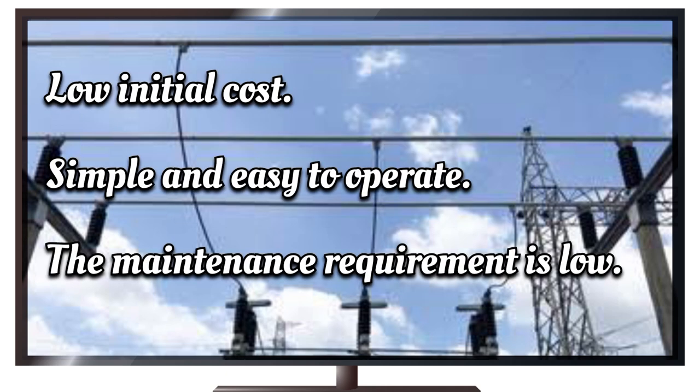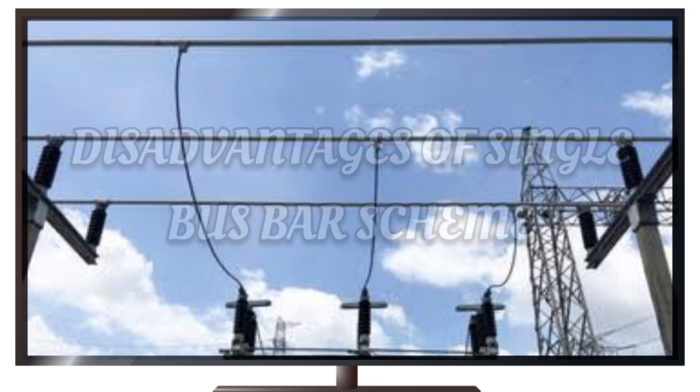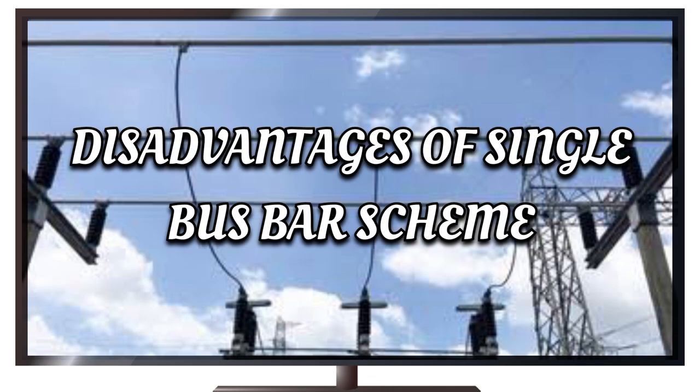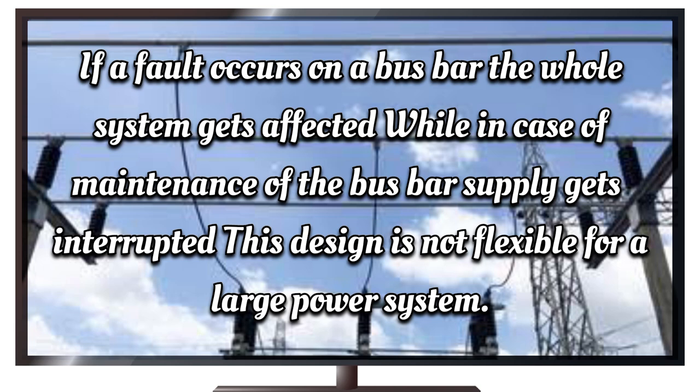Advantages of single bus bar scheme: low initial cost, simple and easy to operate. The maintenance requirement is low. Disadvantages of single bus bar scheme: if a fault occurs on a bus bar, the whole system gets affected, while in case of maintenance of the bus bar, supply gets interrupted. This design is not flexible for a large power system.